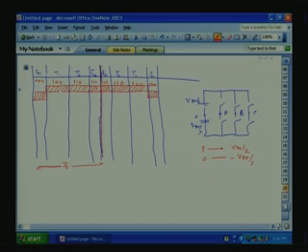So if you see here the switching sequence during the sampling period using volt-second, the switching transitions during the various sub-intervals are selected in such a way that in one sampling interval only one phase changes state, only once, even though the space vectors are changing from 0 0 0, 1 0 0, 1 1 0, 1 1 1. Four space vectors are involved, 2 zeros and 2 active vectors. This is for the A phase, that is VA0.